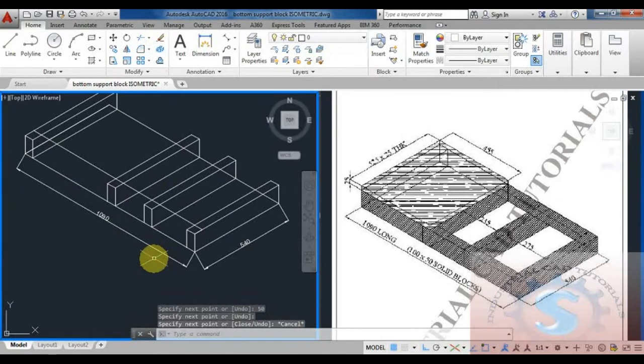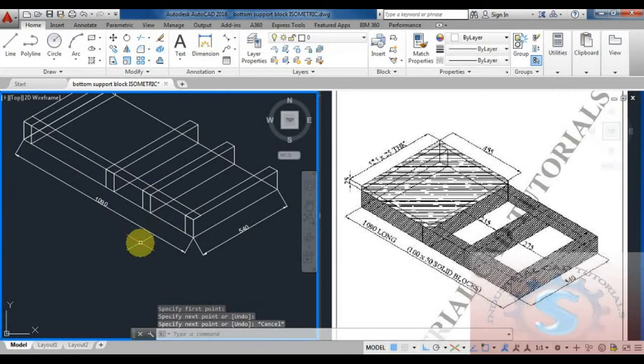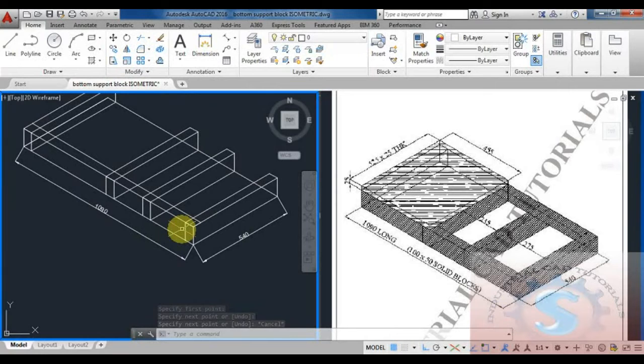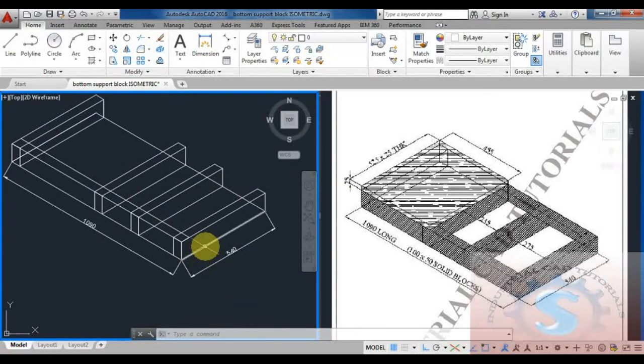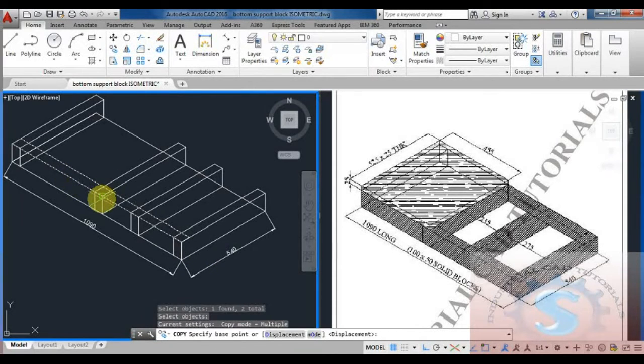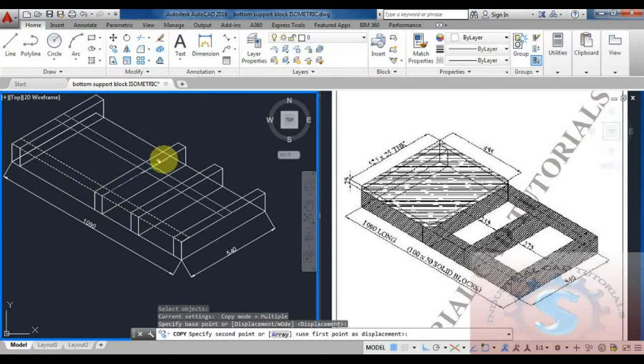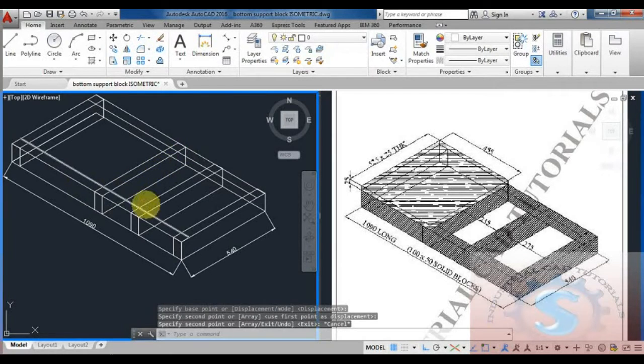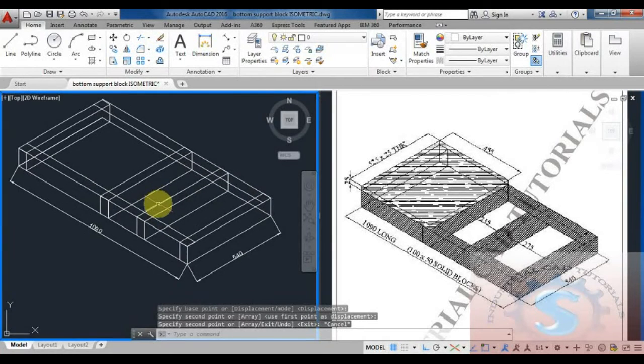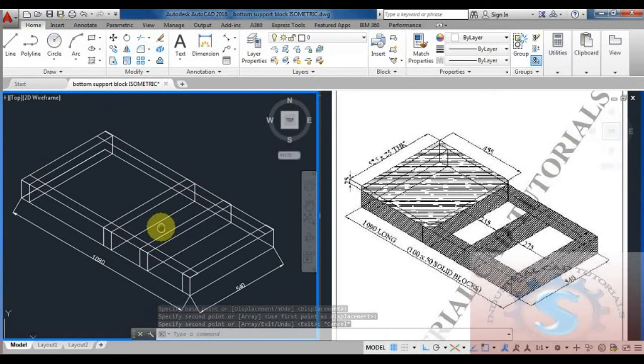Next, I want to give, on the top and the bottom, one big large block. That is nothing but 1090 long. Simply draw the 50 mm distance, intersect the 2 lines to the 2 ends of the blocks, and select the same object to that side also. See, by using the copy command I am doing all the operations. Then one supporting block is completed.